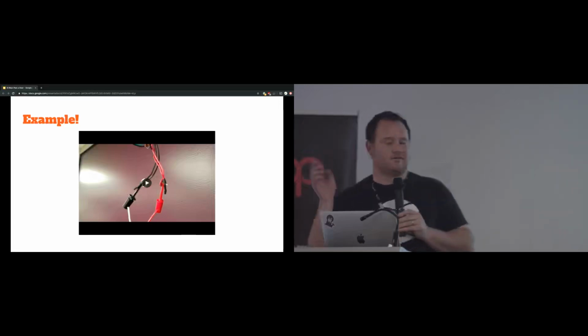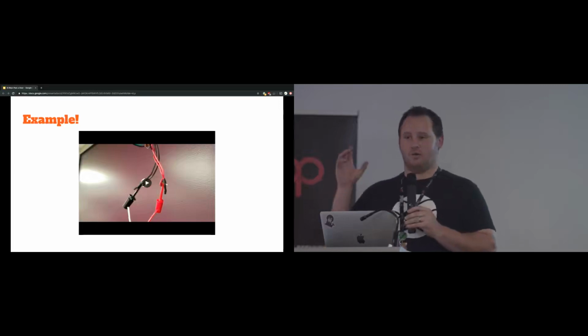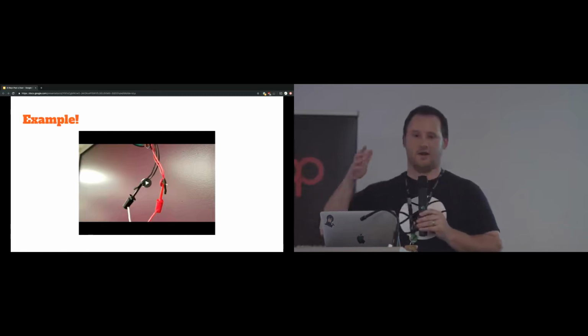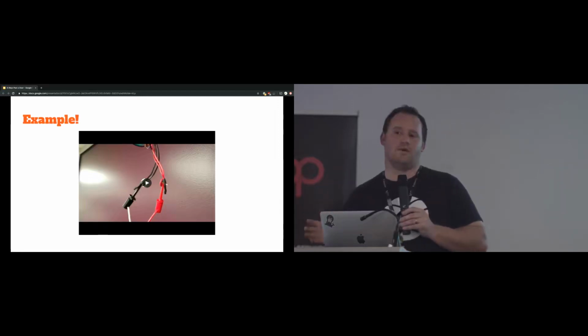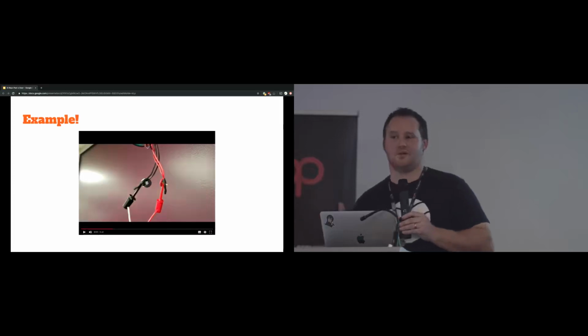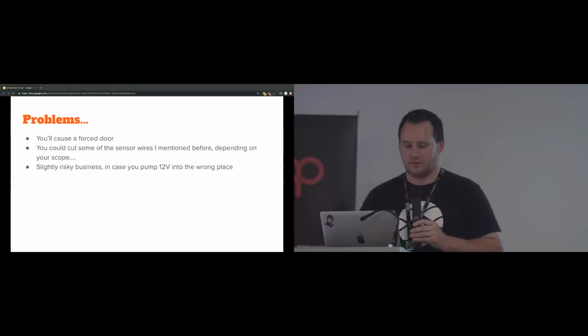Now, noteworthy here, I don't have sound unfortunately, but basically the door access control system was like, something is drastically wrong. I haven't had a request to exit, I haven't had a valid card, anything like that, but the solenoid's been powered and that door's come unlatched and then now the door's opened. And so it triggered a forced door alert and the card reader started furiously beeping and all that kind of thing. So you could get around that, since you've got access to the wiring, by bridging out the wires that do the door state sensing and maybe cutting some more wires, if the client doesn't mind you cutting a few wires, that kind of thing. Let's jump over here.